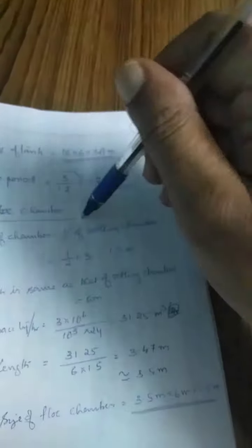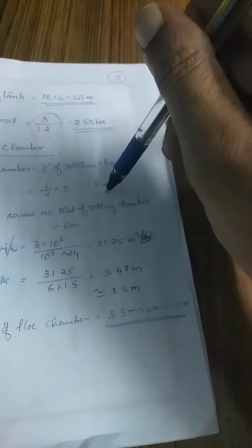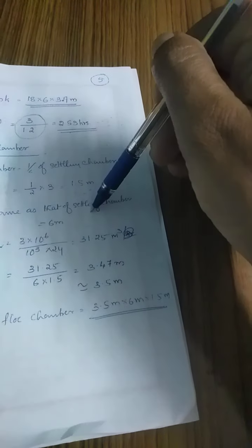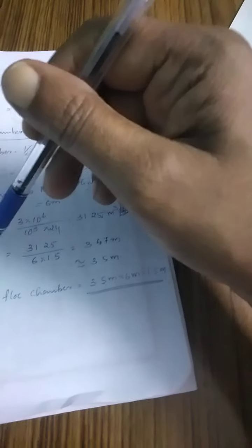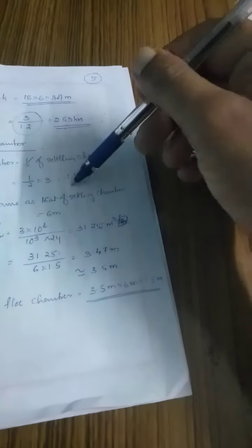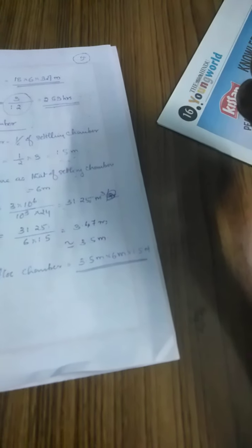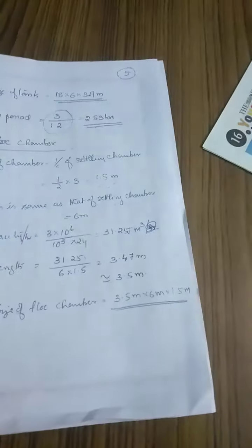Next one, design of flock chamber. Here depth is also same. Depth is half the depth of settling tank, that is 1.5. Width is same as we designed earlier, that is 6 meters. Then capacity of tank, we got length is equal to this area divided by this capacity, that is 31.25 divided by 6 into 1.5, that is 3.5. Size of flock tank is